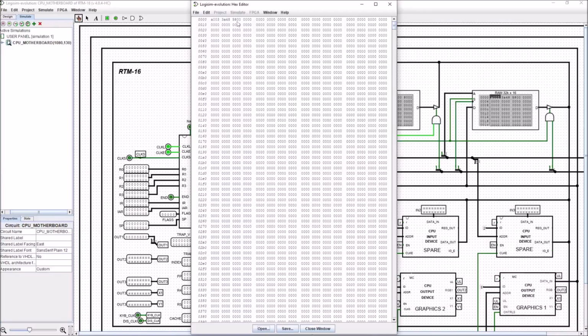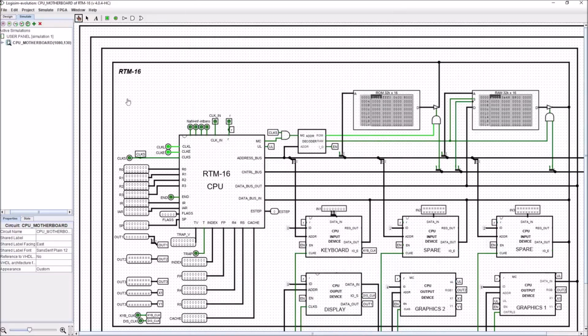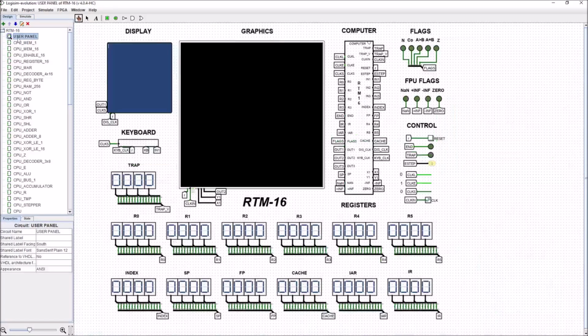And then the next memory location is going to contain the final instruction, which is our end instruction, which is 5800. So what we can do is we can actually work through this instruction one clock pulse at a time. So we can start clicking through. Now we're only interested in it whenever we're getting the instruction, which is going to be the A3 instruction. Okay, so it'll be A003.